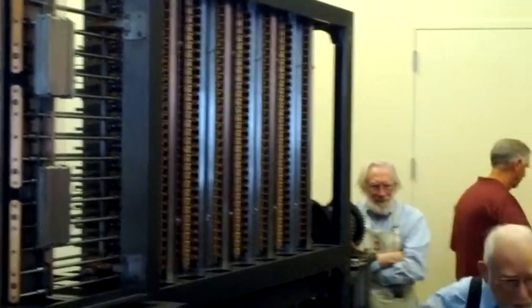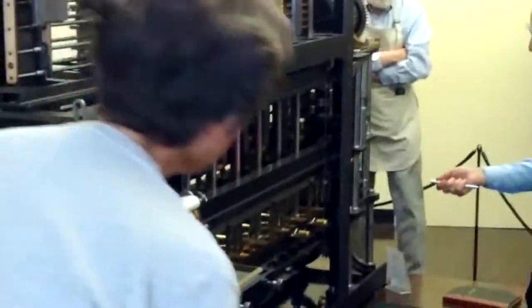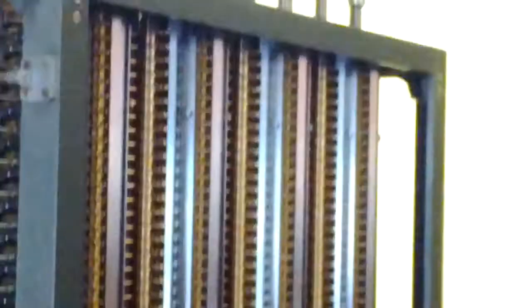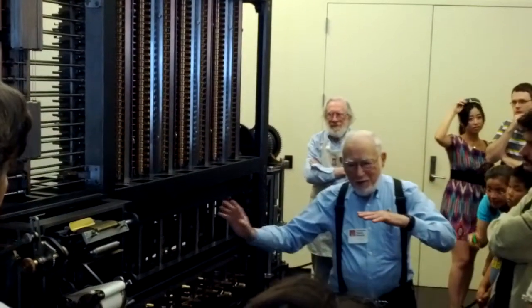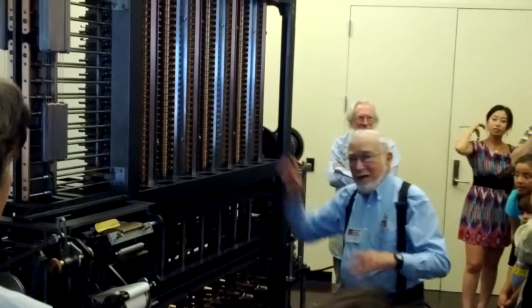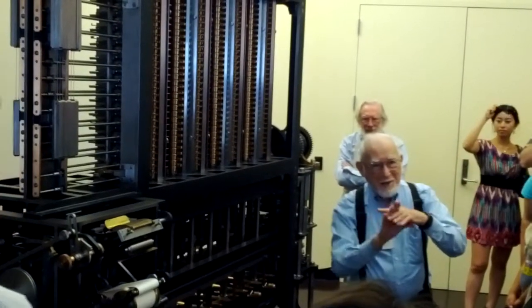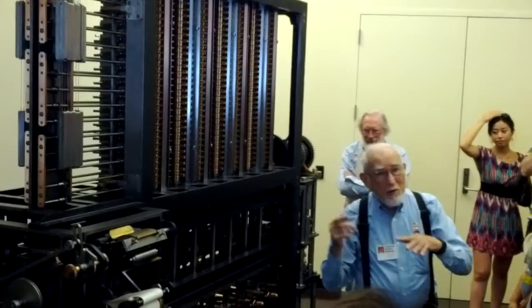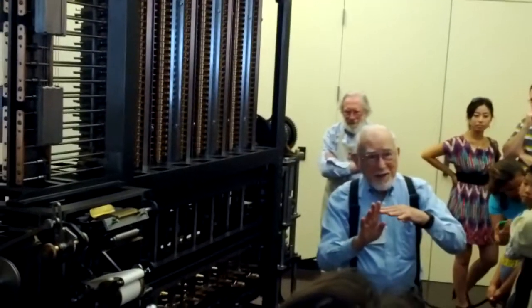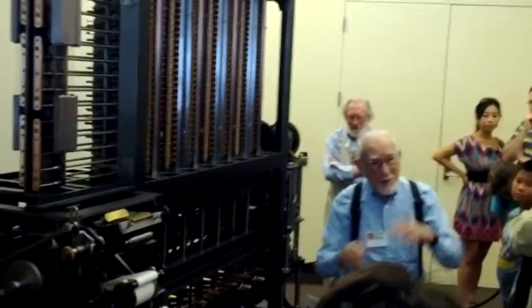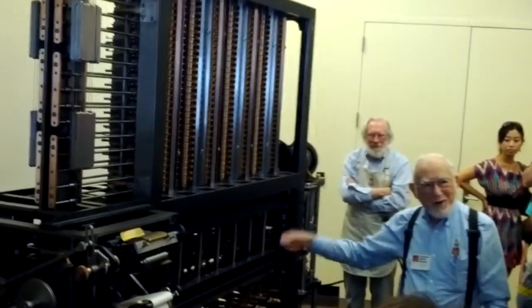Now, finally, the thing which makes all the noise. See this? My rundown is there's a sharp edge here on the right, relatively sharp. It goes the whole length of the machine. And after addition, remember, these things are sloppy. That thing comes slamming into the teeth, and it digitizes, actually makes accurate the position of the wheel. And one of the ways this machine can jam is if somehow the lock hits a tooth dead center. Then we're dead. We have to undo a screw and free up that lock.